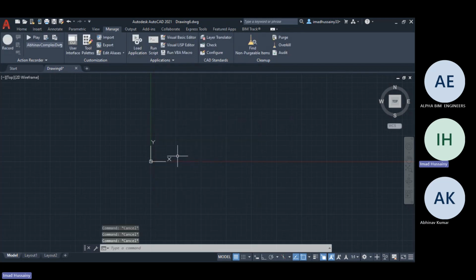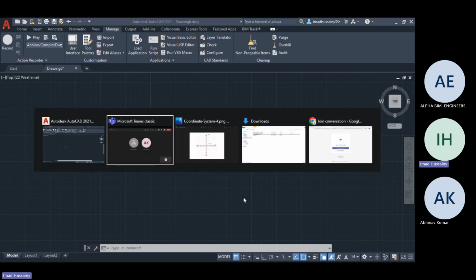You have to note it down. UN for units, L for line, and we have seen that in order to bring back your command line, Control 9, and Control plus 0 is to hide all the tools on screen, a full screen view. And where you can take your UCS, WCS. Now, if somebody gives you nothing in your AutoCAD screen, I think you can bring it back confidently now, right? Yes.